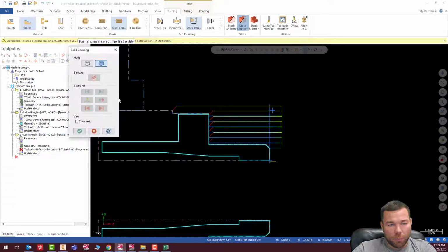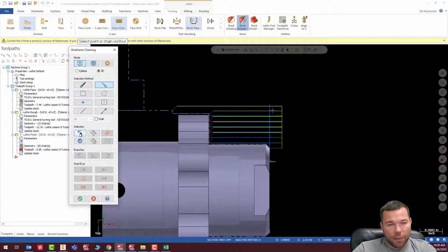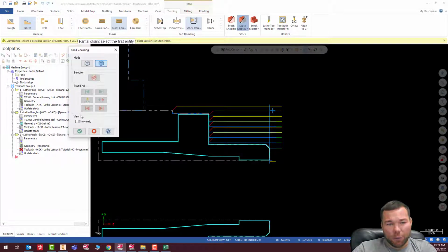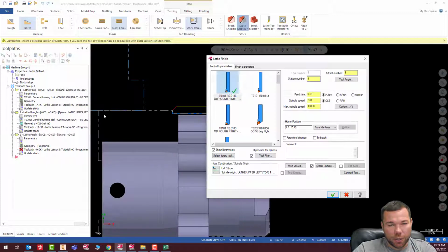Let's finish up here. I'm just going to do my same one. Unfortunately, I do not have that option in here. If I do go back, it won't let me do it then. So I do actually have to reselect because there's not a last button for this, unfortunately. So I'm going to go ahead and select that same path, check, and type in my speeds and feeds, 3000.